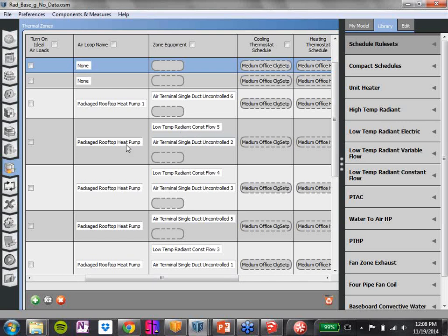You can see that we have a supporting rooftop heat pump, which you'll see, you size your system for a particular radiant load, a radiant system, and then you can add in other systems to supplement that if you're afraid of the thermal lag, occupant complaints, or overheating during the summertime, or overcooling during the wintertime.